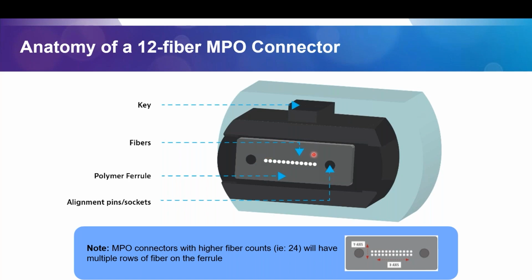I mentioned earlier that some of the other popular configurations are 8 fiber or 16 fiber. So the same thing would apply in an 8 fiber MPO. It would be fibers 1, 2, 3, and 4. And then these aren't there. These are just black, it's the ferrule. There's nothing there. So 1, 2, 3, 4 are blank, and then 4 on this end. So that would be an 8 fiber MPO connector. And then a 16 would be the same. It's just 8 over 8.